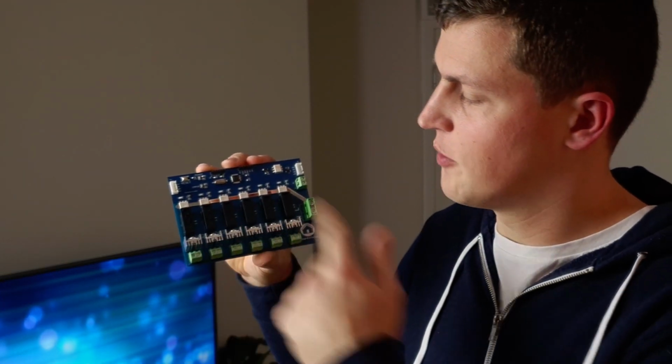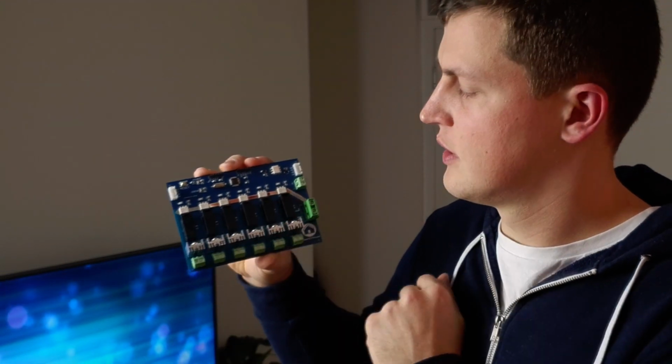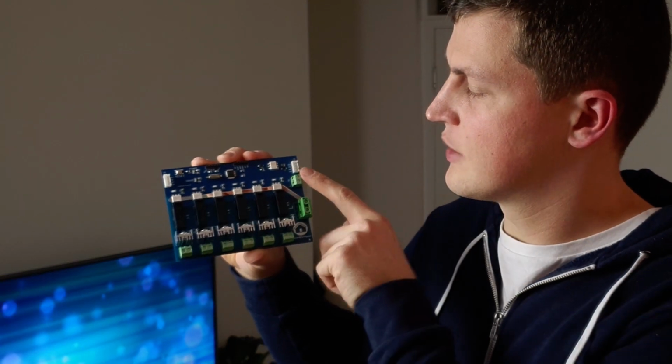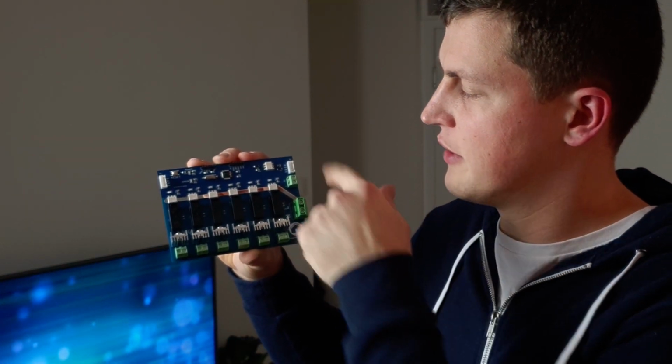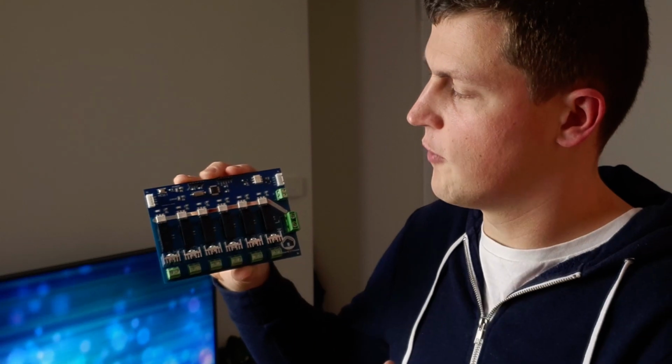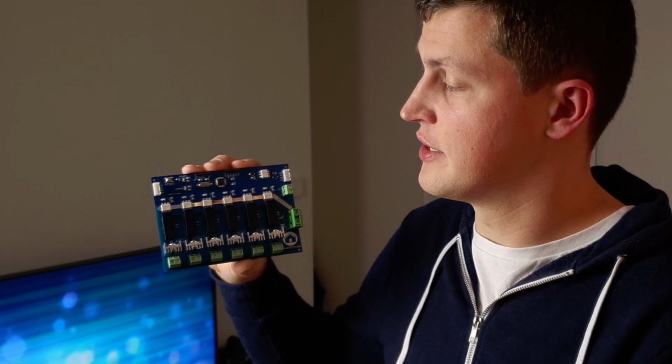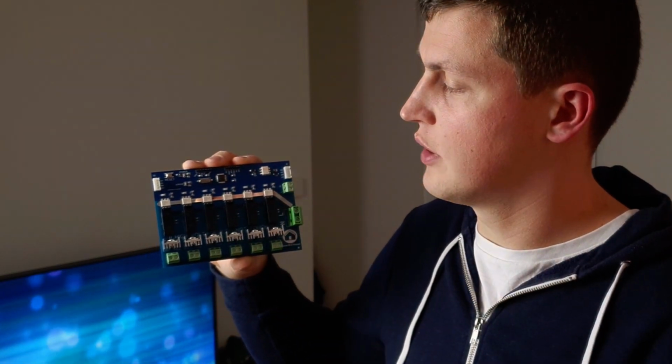So, as I said, I'll only talk about the code in today's video in this microcontroller, but I wanted to give you a quick rundown of what this board is really about. So, as you can see, there's 6 outputs for mains, each having their own fuse. This is the mains input, and this is each individual output. This is the 12 volt AC input for zero crossing detection. These two headers are for 5 volt power and I2C communication. There's a header for serial communication and a header for burning the bootloader on the chip.